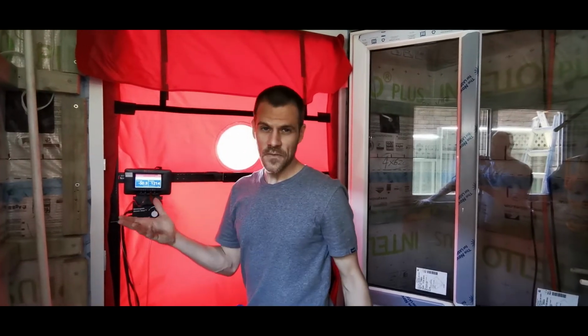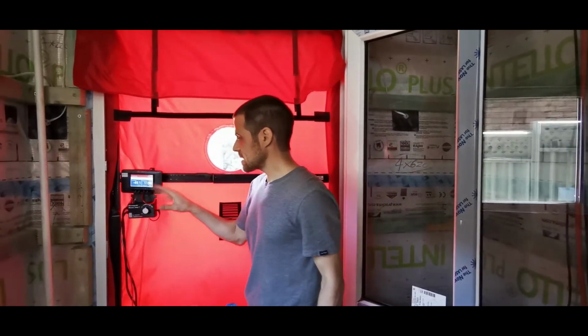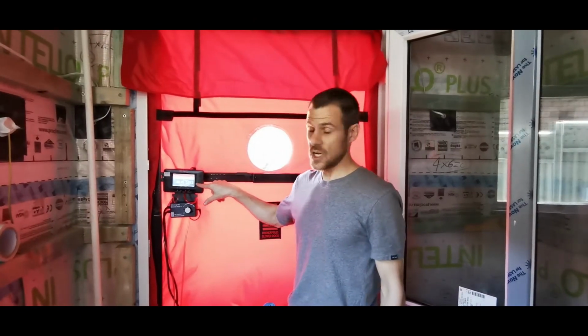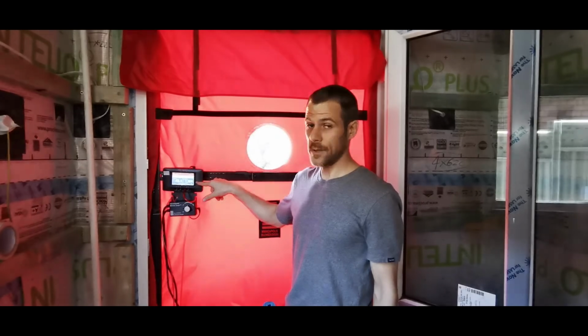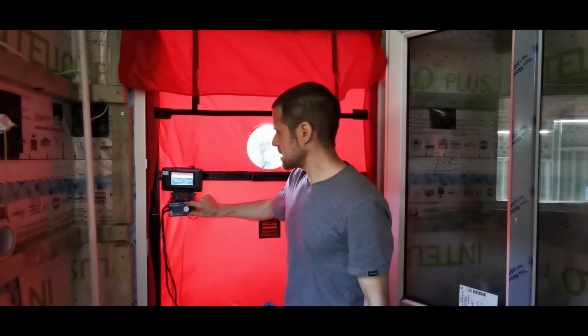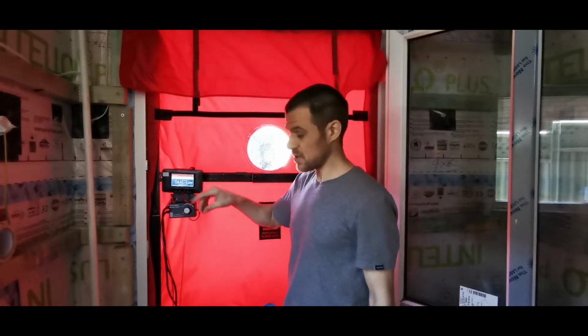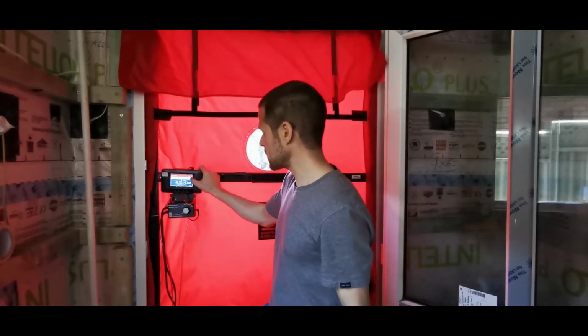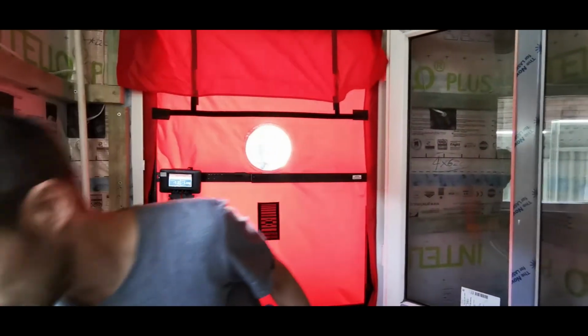So just really roughly speaking, we're around 50 pascals, between 48 and 52 pascals, somewhere around 50. So this is the leakage number right now. It's about 1,200 cubic meters an hour. What I can do is put the fan on automatic mode and tell it to try to stay at 50 pascals. So I'll tell it, go to 50 pascals, and we'll let it do its thing.